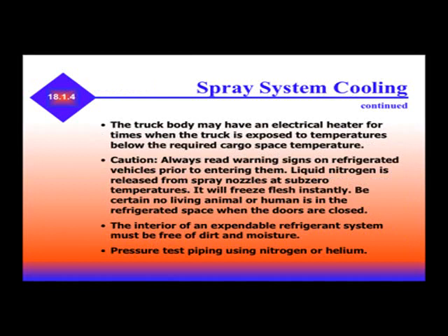The truck body may have electric heaters for times when the truck is exposed to temperatures below the required cargo space temperature. You need to always read warning labels on refrigerated vehicles prior to entering them. Liquid nitrogen released from the spray is at sub-zero temperatures. It will freeze flesh instantly. Be certain no living animal or human is in the refrigerated space when the doors are closed. The interior of the expendable refrigerant system must be free of dirt and moisture. Pressure test piping using nitrogen or helium.